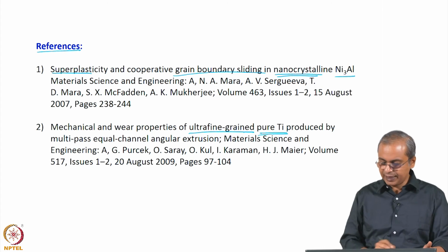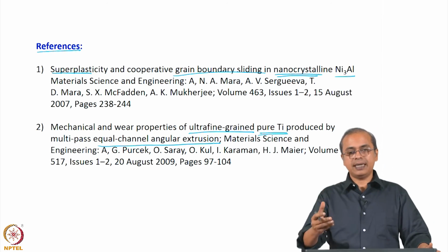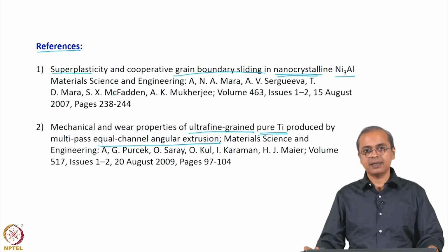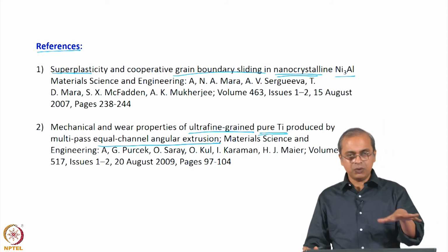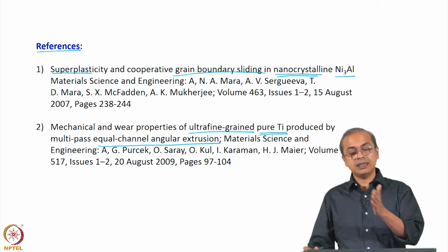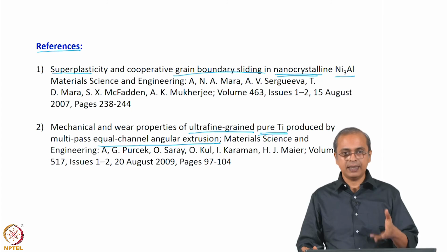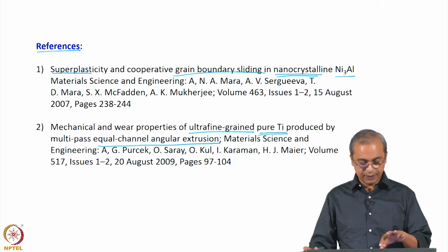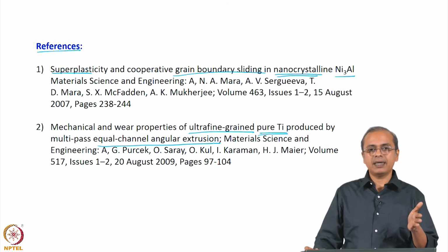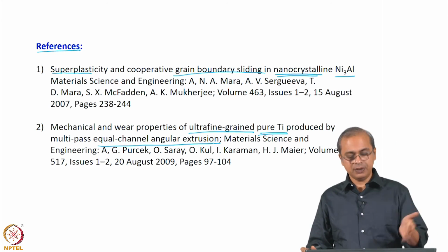So, they look at this ultra fine grained pure titanium and they are using multi pass equal channel angular extrusion to get that very fine grain size in the nanocrystalline range, and then they study it for both mechanical properties and wear properties. They do the kind of testing that we have discussed in general in this class. You can see the specific data that they get, the specific plots, and the microstructures that they obtain in that journal paper. And you can see they have a particular situation where they see an improvement in mechanical property, but not an improvement in wear property, and they propose theories for it.